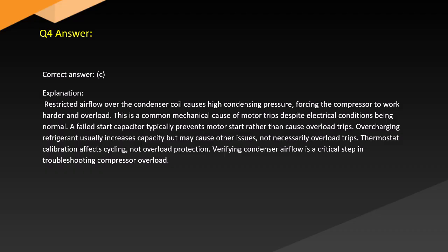Answer. Correct answer: C. Explanation. Restricted airflow over the condenser coil causes high condensing pressure, forcing the compressor to work harder and overload. This is a common mechanical cause of motor trips despite electrical conditions being normal.